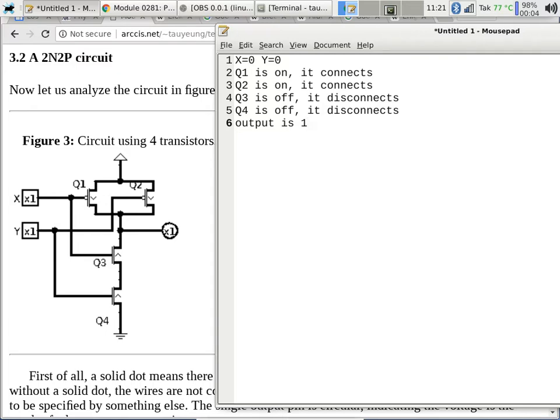So now when you trace from the output pin, it has two directions to go. But this path here, going south, doesn't connect to anything, right? But when you trace the path to the north, it can go through this, and both of these paths are connecting. So now you have a really good connection to the positive voltage. And that's why the output pin is going to have a positive voltage.